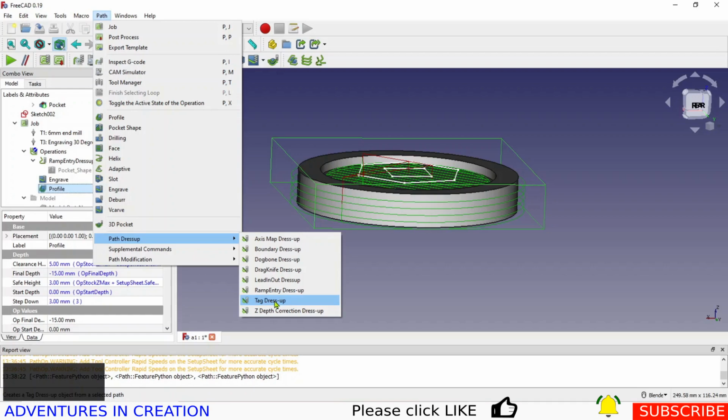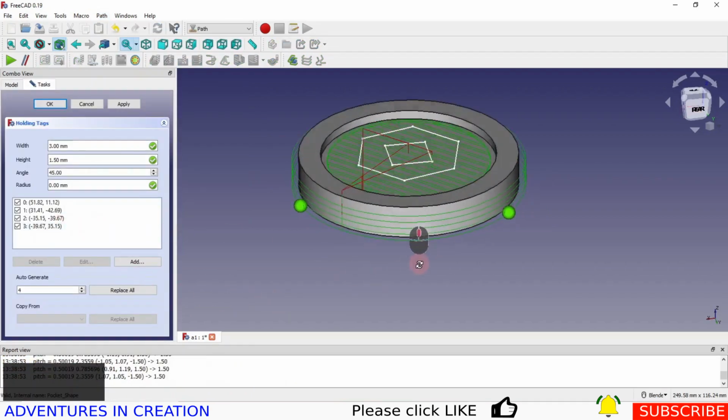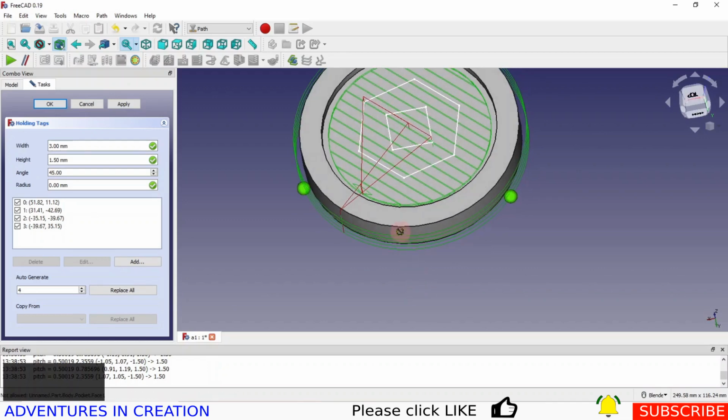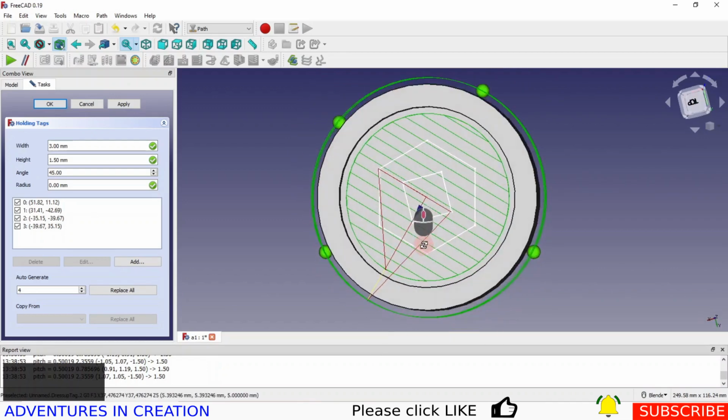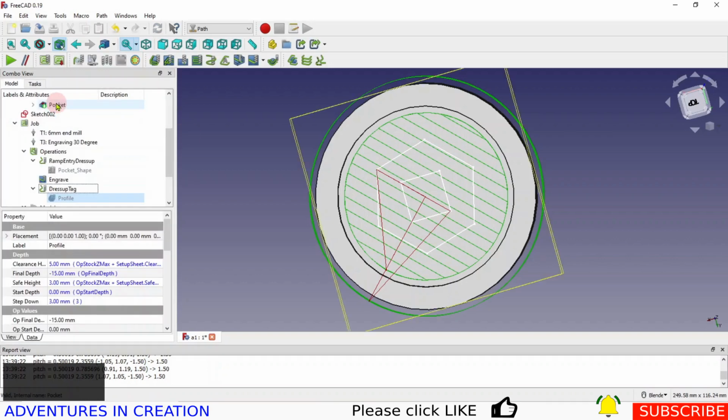tag dress up. So the tag dress up gives us these little tags. And if I rotate that guy a little bit, you'll see where it's placing them. So I've got 4 in there at the moment, and I think that's plenty. What it's going to do is leave a little bit of material there just to hold that guy down. That material is going to be 1.5 millimeters tall. It's going to be 3 millimeters wide, an angle of 45 degrees. I think that's going to look great. So we're going to say okay to that, and we're going to accept that.